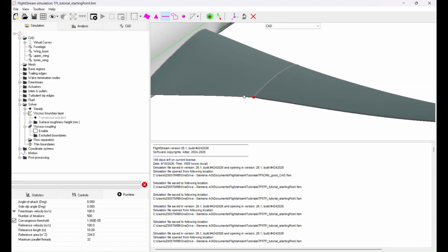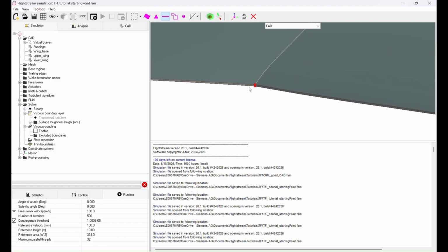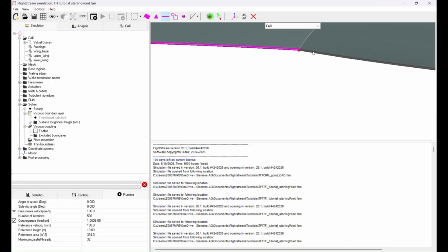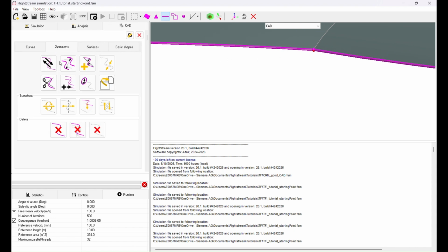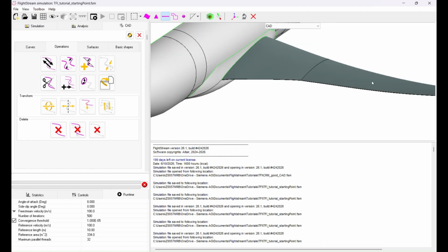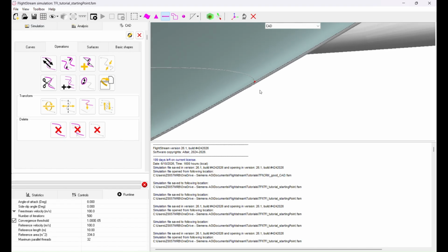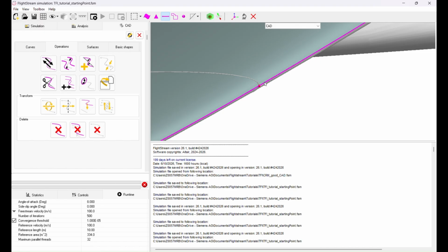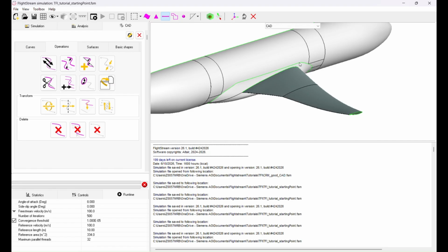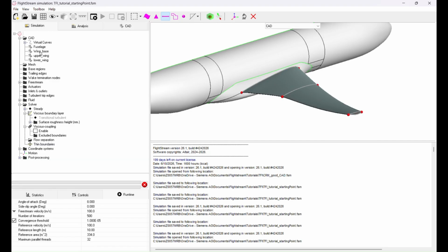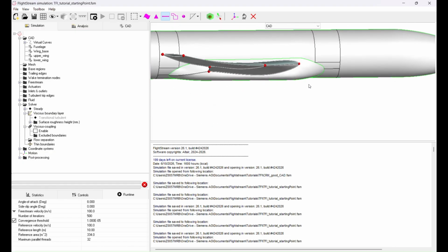Due to this model, we're going to need to remove some of the curves that were transferred as they're going to overlap with others. The upper and lower component both share this curve, so we're going to remove one from each, so there's one remaining. Now we can transfer the curves for our wing base, and we have all the curves that we need for our wing now.